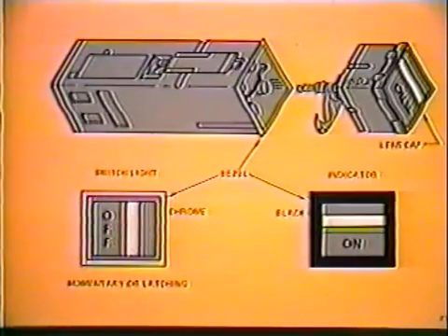A switch light assembly consists of a switch with a lens cap. The lens cap may display a maximum of 2 legends. The message may be either a word, a flow bar, or an in-transit indicator. A chrome bezel distinguishes a switch. A switch may be of the momentary or latching type. A black bezel distinguishes an indicator only. An indicator has no switch function.